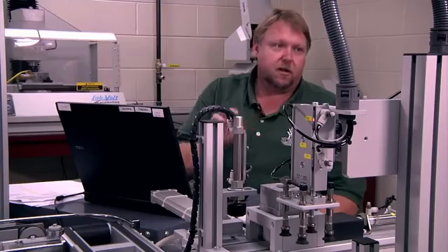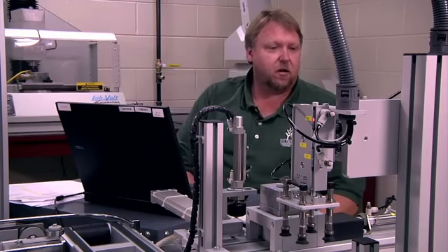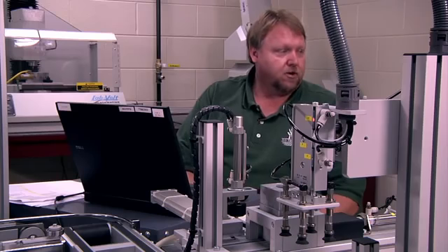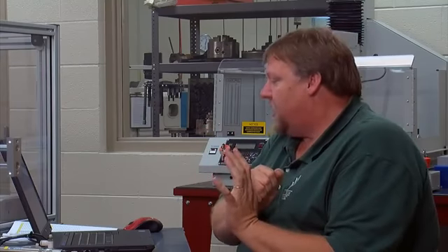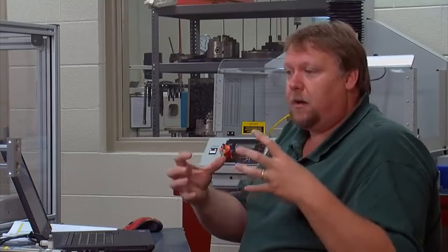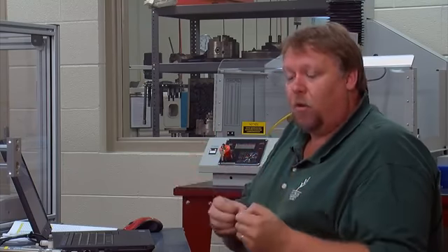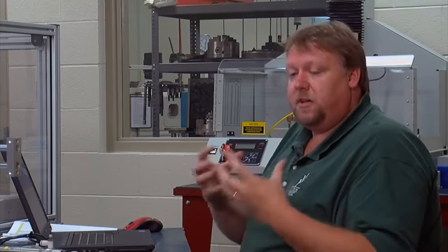So with a station like this, and every one of these stations in here, we know there's certain modes of operation that we're going to need. We need auto mode. We need manual mode. We need reset mode. We're going to need a home position. We're going to need a start button. It's going to initiate things. We might need a parts passed. We might need a parts failed. All those are considered work bits. So at this point you have to think about on the station, how do you want to control it?